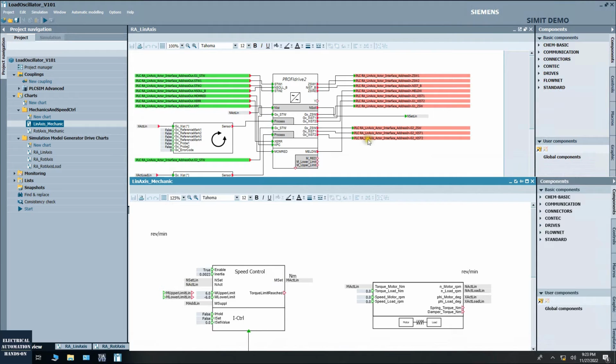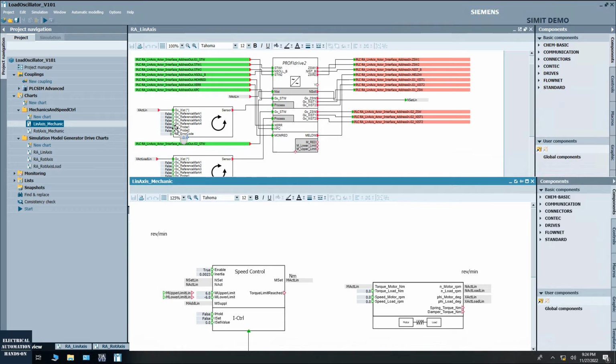This is the motor model. The drive gives a speed command to this motor, and the motor connects to the load. And the load feedback, because the encoder connects to here, we have the second encoder, right? Then for the second encoder, we will see this X actual linear will be connected to the encoder here. But the load degree will be connected to here. So basically, those represent the encoder, the degree feedback goes to this encoder input.